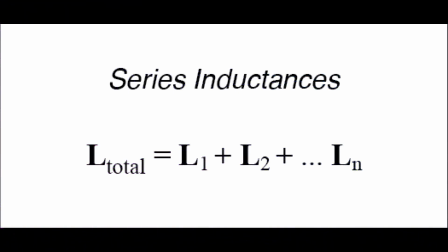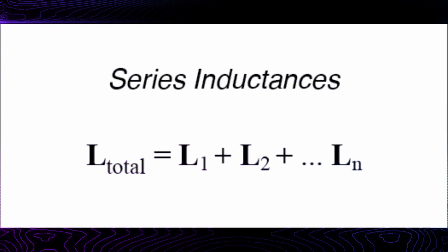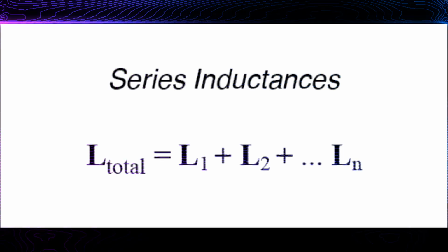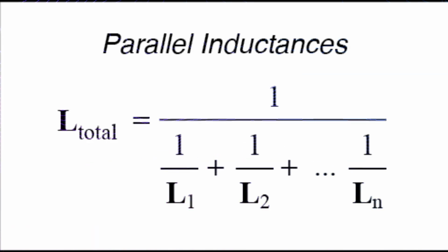All inductors have some amount of resistance. Inductors that have a Q of 10 or greater are generally considered to be pure inductors. Once the inductive reactance becomes 10 times as great as the resistance, the amount of resistance is considered negligible. For example, assume an inductor has an inductive reactance of 100 ohms and a wire resistance of 10 ohms.